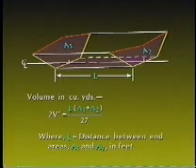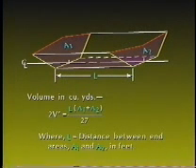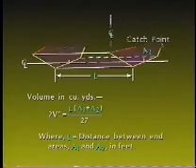On this sketch, the red lines represent the ground cross-section, while the yellow lines represent the typical design section. This case is an example of a through cut, which is a section without embankment, only excavation. Quantities are calculated by first computing the areas of sections A sub 1 and A sub 2. This can be done by using the coordinate method for computing the area of a polygon.